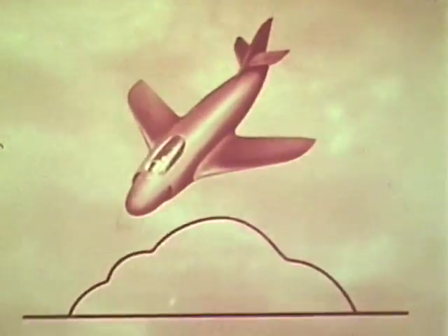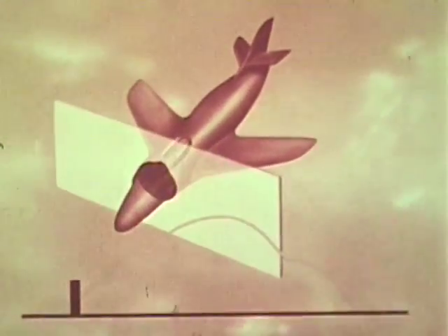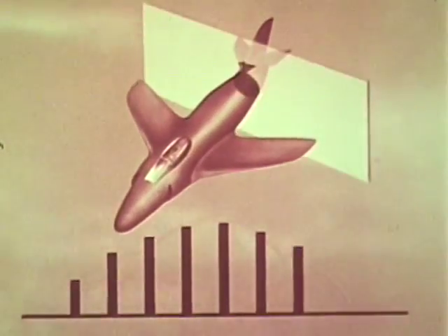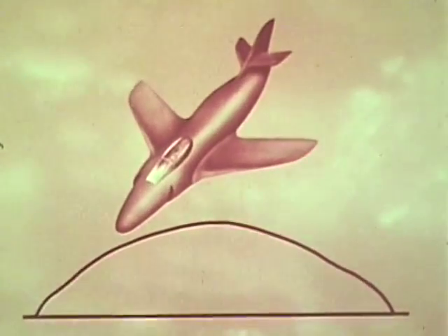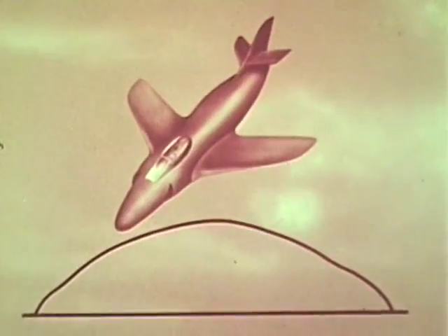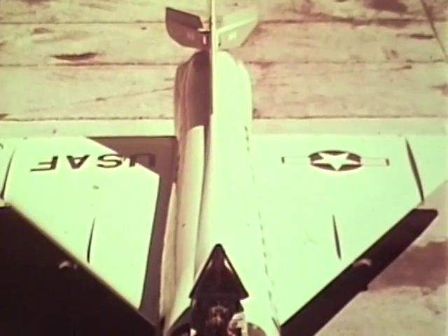Let us redesign the aircraft to smooth out the bumps in the curve, so that the cross-section area changes gradually and not abruptly. So instead of the curve with bumps, a much smoother curve is obtained. This means the fuselage must have a waist to compensate for the wings and must flare out again behind.